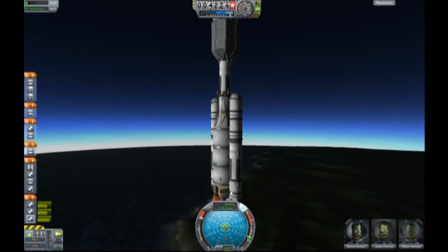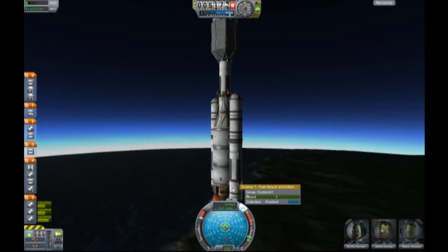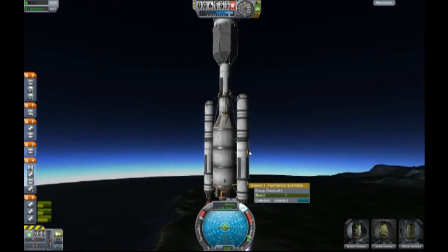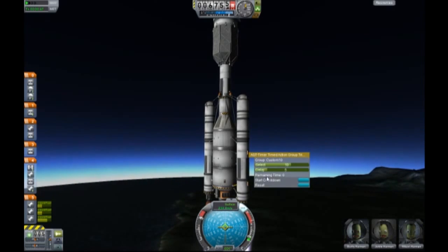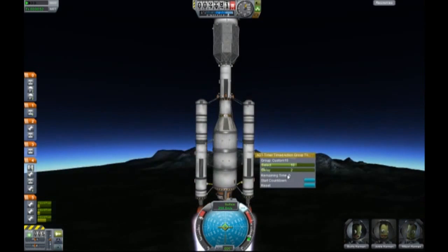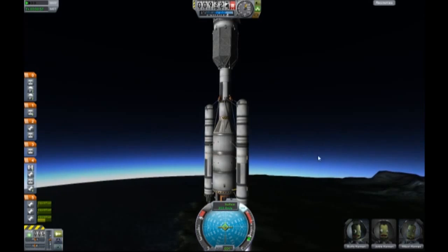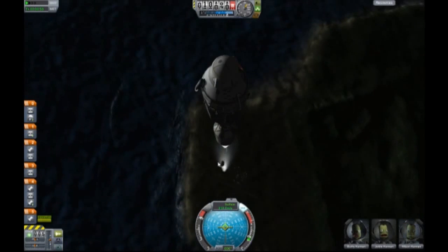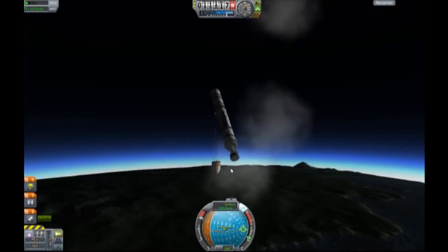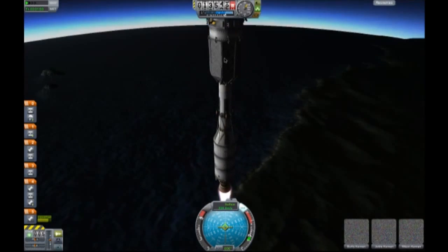the other rocket boosters a little bit closer. So first we have here a fuel sensor that will fire when the last bit of fuel has drained from this tank, and it will also fire a timer, and after a delay of 5 seconds, well, let's make it a bit shorter, make it 2 seconds. Well, this is just 1.5 seconds, that's okay. It will fire the parachutes, so that the parachutes don't go dancing like crazy. So you see both boosters have deployed the parachutes, and we're back at the rocket.